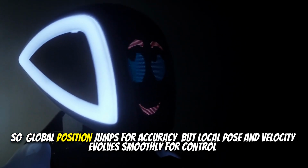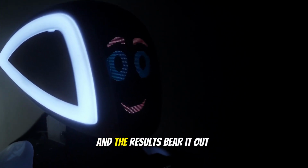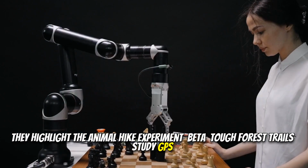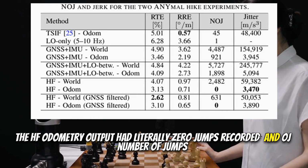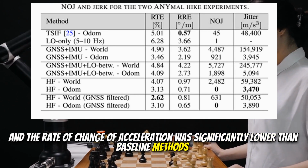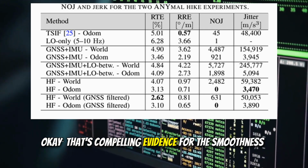So global position jumps for accuracy, but local pose and velocity evolve smoothly for control. That's the guarantee. And the results bear it out. They highlight the animal hike experiment, tough forest trails, spotty GPS. Yeah. The HF odometry output had literally zero jumps recorded, NOJ, number of jumps. And the rate of change of acceleration was significantly lower than baseline methods. That smoothness is exactly what you need for controlling something like a walking robot. Okay, that's compelling evidence for the smoothness.